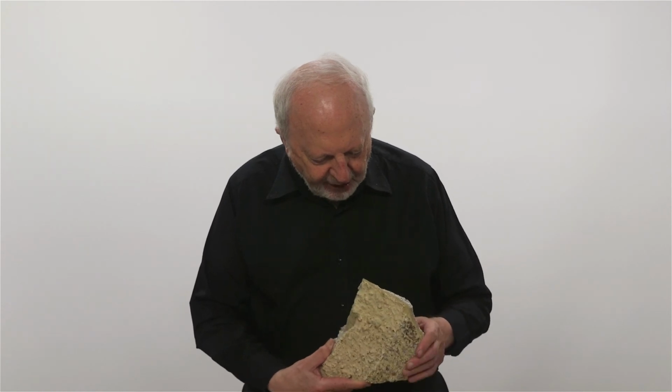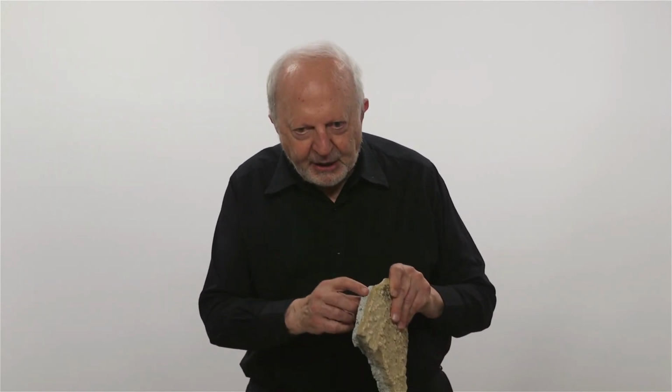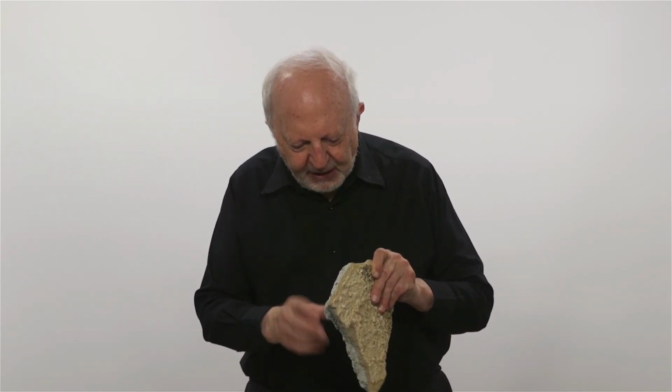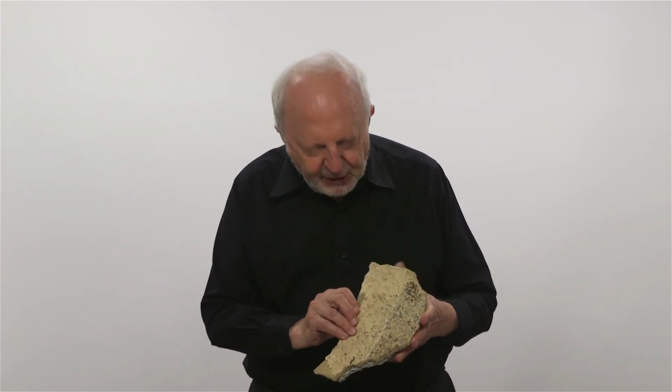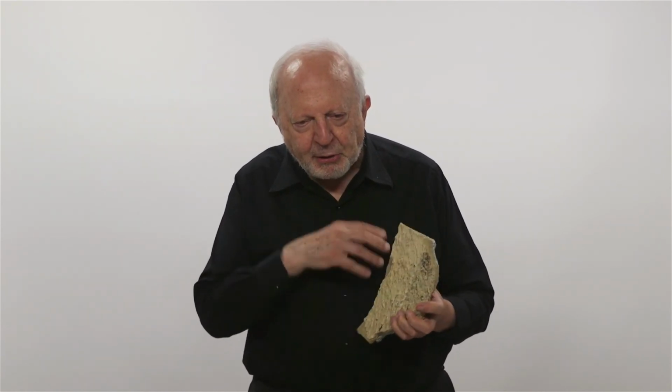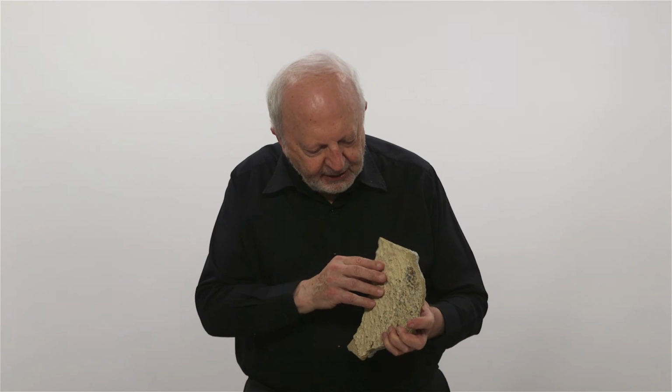On the face of the wall in the 20th century, you might, in the Arts and Crafts tradition, try and make it look cottagey by having a finish like this. This is rough cast. So it has perfectly ordinary cement render first, and on the face of it, this finish, which has small stones and has been thrown against the wall to give a sort of rustic effect.